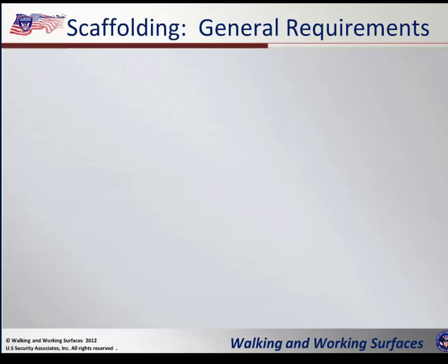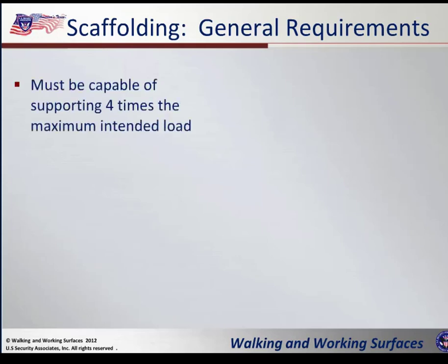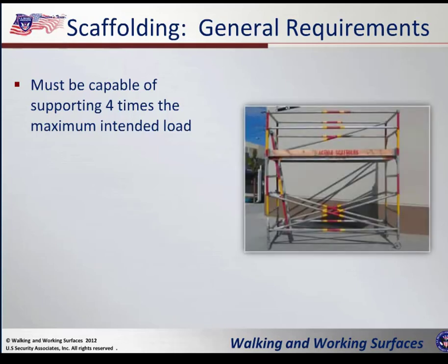Okay, let's move on and talk about scaffolding. General requirements. Now, again, you aren't going to be putting up scaffolding, but when you're doing your rounds, you can see if anything looks wrong. What general requirements are, first, the scaffolding must be capable of supporting 4 times the maximum intended load. Do not alter or move it when you are using it.